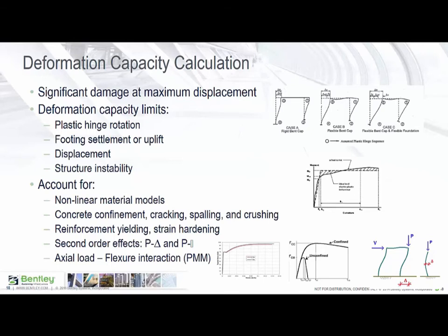The displacement capacity calculation should consider nonlinear material models, concrete confinement, cracking, spalling, and crushing, reinforcement yielding, strain hardening, second order effects, large and small P-delta effect, axial load flexure interaction.